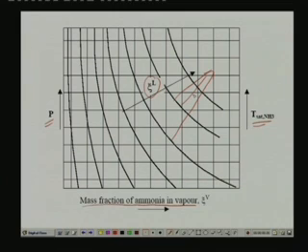So, if you know the concentration of the liquid, for example, let us say that this is the concentration of the liquid and this is the pressure, then you can easily read what is the concentration of ammonia in vapor phase. Similarly, you can find out from the pressure and solution also. Such kind of charts are available in literature, using which you can find out the exact composition in vapor phase from the knowledge of liquid phase composition and the pressure.